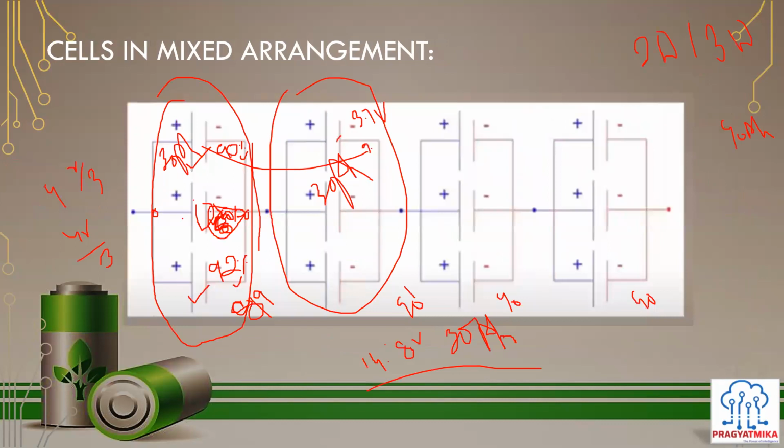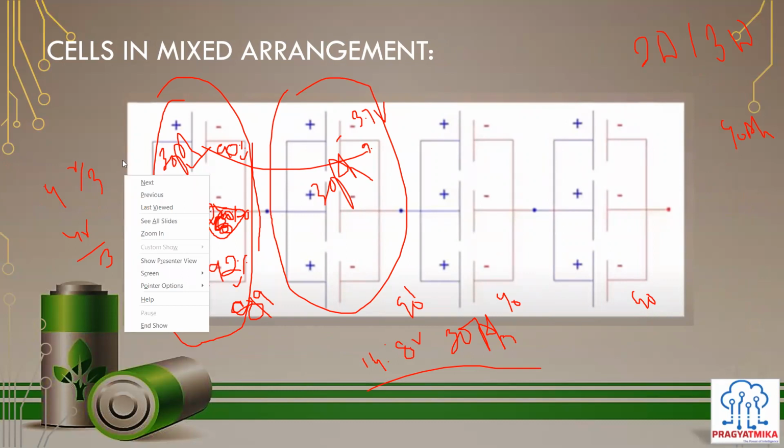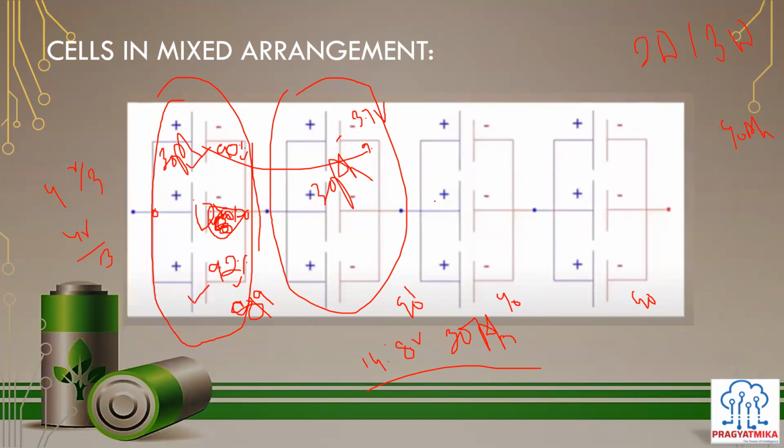Actually, practically, this method is used. If you take any battery pack and open it out, you will see that this is the method used. Okay, because it is the region of the BMS. Say it is a 10S battery pack we are going to make, for example. So in the 10S battery pack, you will have a total of 10 such points for the measurement.